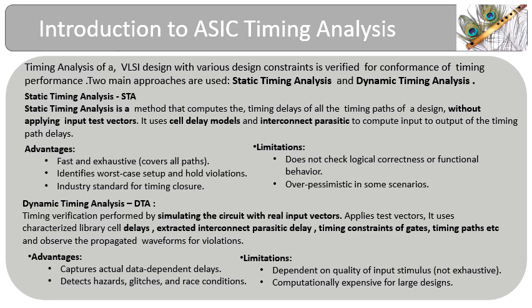Static timing analysis, or STA, is the backbone of timing closure in VLSI design. It computes delays across all paths, without needing input vectors. STA is fast, exhaustive, and pinpoints worst-case setup and hold violations. But it doesn't verify logical correctness or functional behavior.